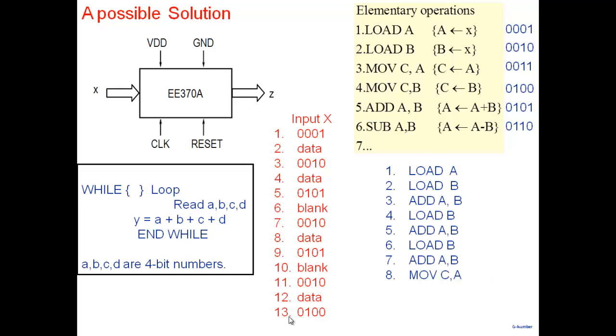And after that, what I can also do is, let's say after going through all this, the system goes back here. We have not done that. We can, for example, add an operation where you reset everything. So we can add an instruction called reset. It sets all the registers to 0: A to 0, B to 0, C to 0, D to 0. So after doing all this operation, you can do a reset and then go back to the first stage here. And then it keeps on looping, right? Keeps on executing. So by using these elementary operations, we have executed this particular custom task that you wanted to do through these elementary operations.